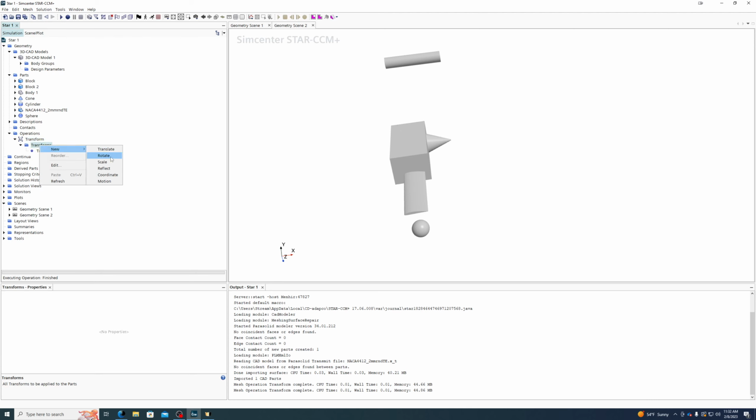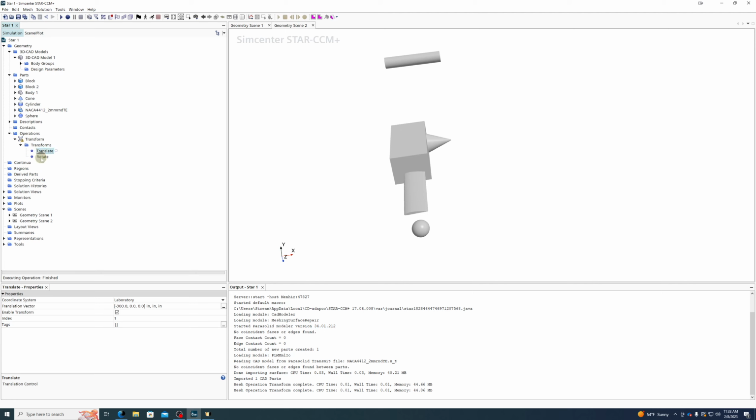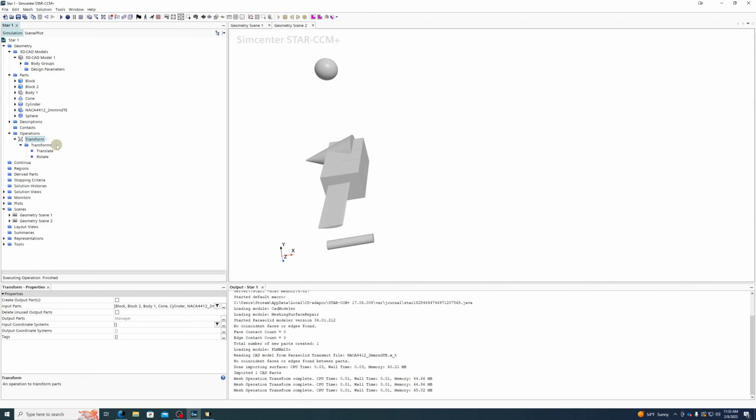We can also add more transformations if we want. We can tell it, after translating, go ahead and rotate about some origin. Let's do -400 0 0 inches. Rotate about the z-axis, so 0 0 1 is the z-axis. And let's do 180 degrees. And it all flipped over.